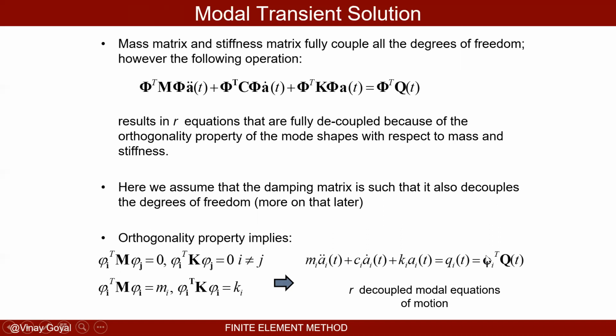We turned a fully coupled finite element model with millions of degrees of freedom, with millions of eigenvalues and corresponding mode shapes. And I want to figure out how the aircraft deforms due to forcing functions applied to it, maybe from aerodynamic loads. But I maybe say, okay, out of all the mode shapes, maybe 25 matter.